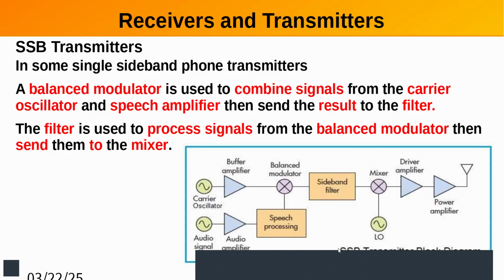So for a multi-band transmitter, the only thing that would change is this output part, what frequency band you're going to shift it to, because the other part is going to be the same. You're really generating it at an IF frequency, and then you're going to do a frequency shift.